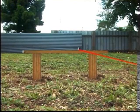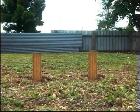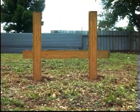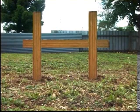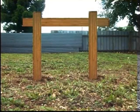Where the pegs are longer and the ledger is fastened to the sides of the pegs, the profile is called a hurdle. The longer legs allow the height of the ledger to be adjusted up or down during levelling procedures. It is good practice when using a hurdle to have the tension string line pull the ledger against the pegs rather than away from the pegs.